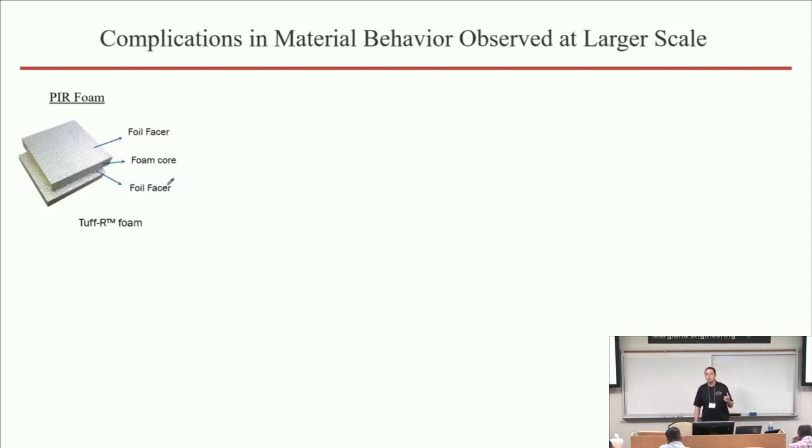It's an insulation material that goes inside of those cladding panels that are put on the buildings and sometimes spread fires really well on the building. Now, I do want to point out that PIR foam by itself is not a particularly flammable material. It's actually pretty flame resistant, but in these systems it's also combined with polyethylene, which makes it an interesting